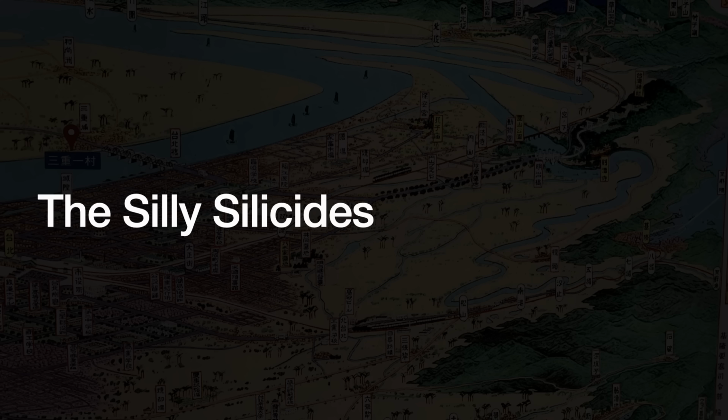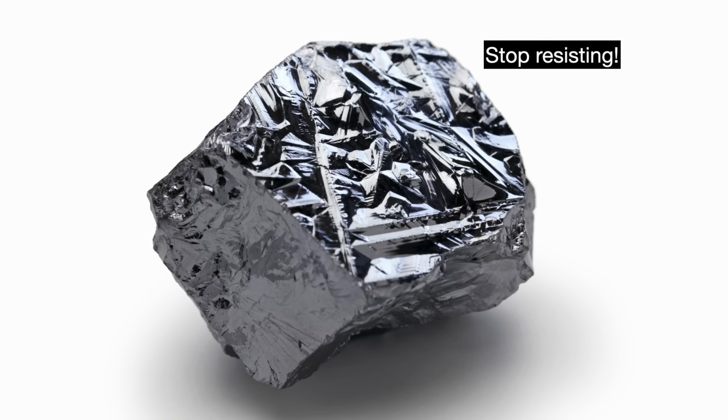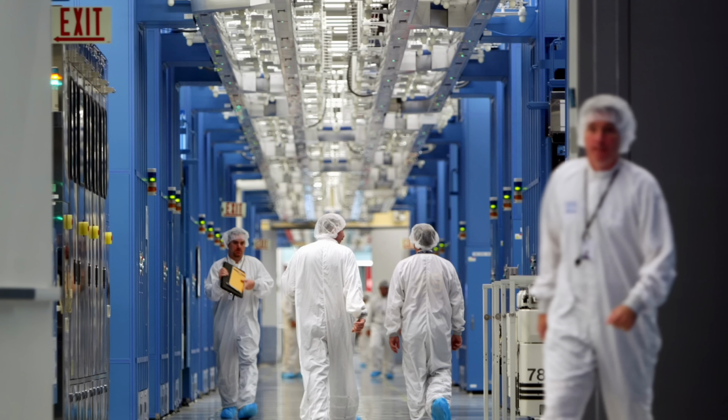As I mentioned way earlier, the transistor is wired up to the interconnect network, and the points where these wires make contact with the transistor are called contacts. The issue is that doped silicon and polysilicon are fairly electrically resistive, which slows down performance and generates excess heat. As transistors shrank, their interconnects and contacts shrank too, which makes the resistance even worse. When the interconnects got to be below 1 micrometer wide, the resistance value got too high to be ignored.